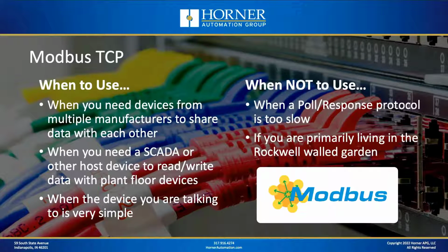It's a protocol you'll find very prolific in both PLCs and host software packages, and is often included for free with those host software packages. So that's another big advantage. If the device you're talking to is very simple, that's another time to use Modbus TCP, because there's a pretty good chance that that simple device has at least implemented Modbus or Modbus TCP as its protocol.